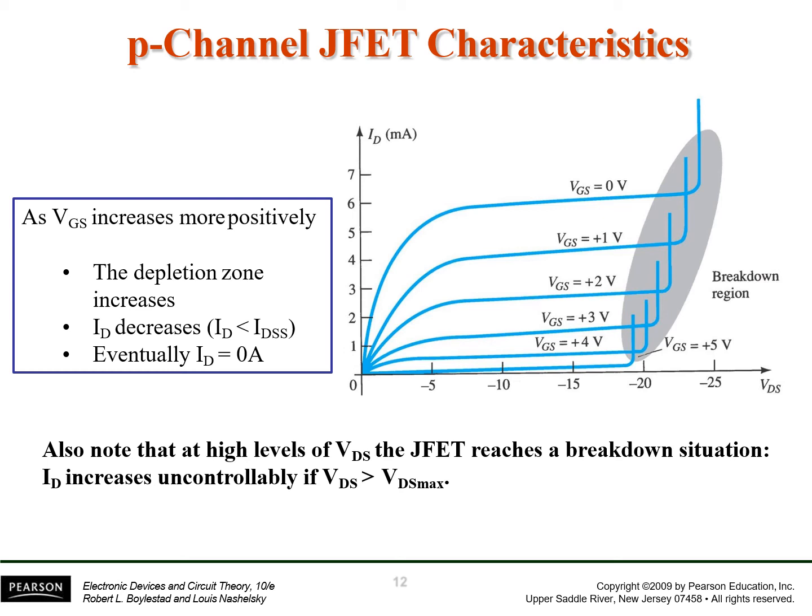This VDS maximum is controlled also by VGS, and if we increase the value of VGS, this breakdown point or VDS value comes earlier, as you can see in the above diagram.